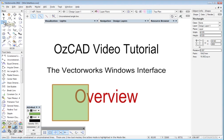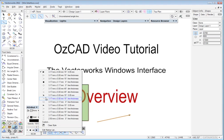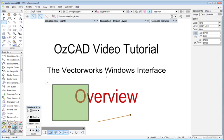And if this was a line, arc, open polyline or open polygon, then the other controls at the bottom here allow me to turn on the arrow or turn off the arrow at either end of the line. And if I do have the arrow turned on, I can also set the style of the arrow by clicking to the right of that, and I can set the style of the arrow.